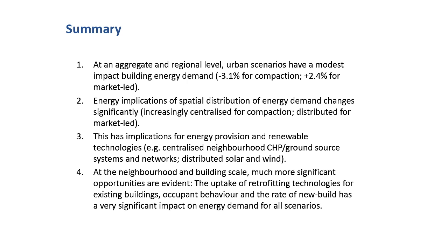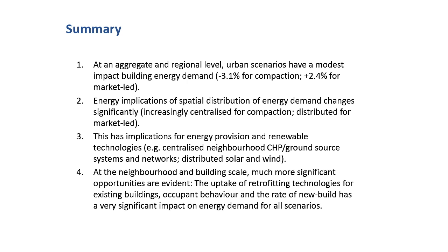And I suppose if I were to come to a conclusion, these are the key points I would like to make. At the aggregate level, at the large regional scale, the basic patterns of urban development make relatively little difference in terms of the energy demand in buildings. And in fact, the same happens to be true for transport. We had transport modelers modeling the same effect, and it's more or less true, a 5% variation of effect for transport energy. That's largely because the infrastructure is there, and it's not going to change very quickly, even in 30 years, even if you have a complete policy dominated around compaction versus market-led policy.